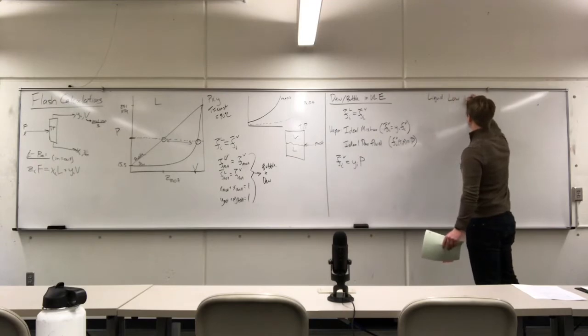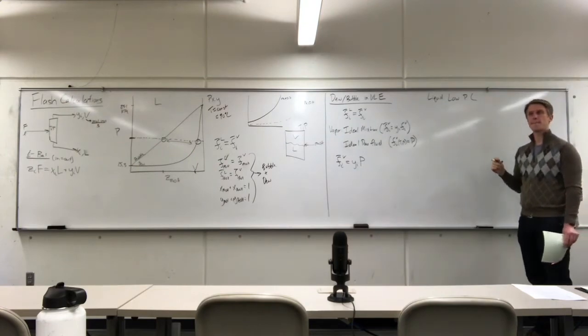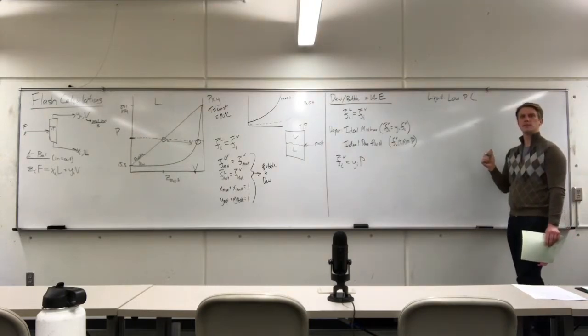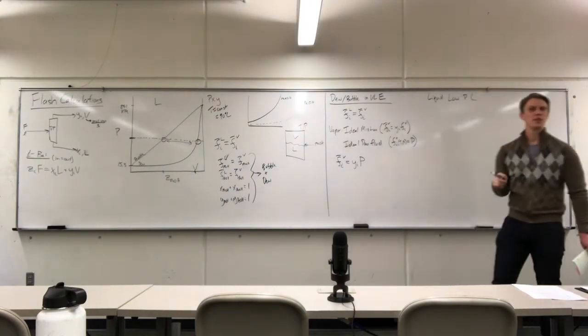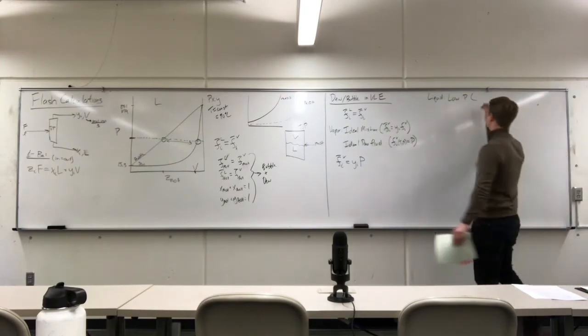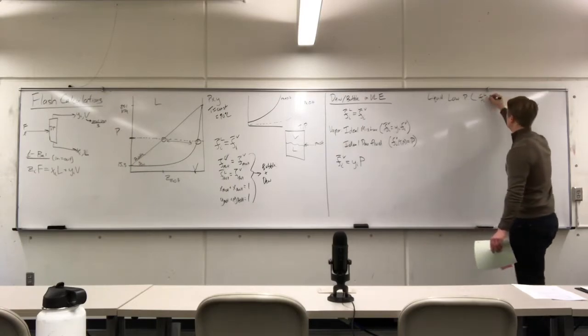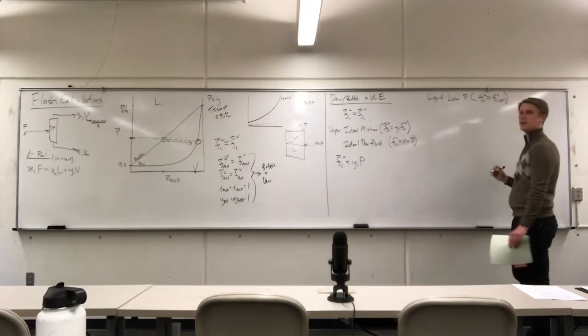We're first going to assume low pressure. If it's low pressure, what does that mean we can approximate here? What does low pressure allow us to do? We'll do that in one step, just one step before that. If it's low pressure, we can ignore the Poynting correction. If we ignore the Poynting correction, that means that the pure fugacity of the liquid is approximately equal to the fugacity of the saturated liquid.